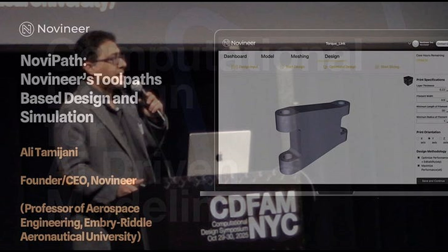And then we find the elements that they have. The center of the element is between those sections. And then we assign the property from the filament to the element for that specific section. For example, in that section, A, B, C, D, all of them will have theta 1 orientation because they're all located in that section of the filament. Then we can patch them, several sections, put them together, depending on how close the orientations are.